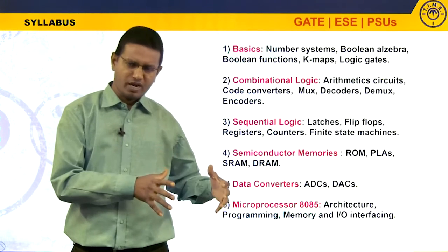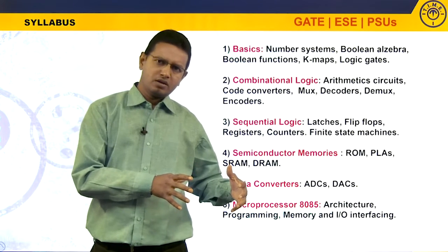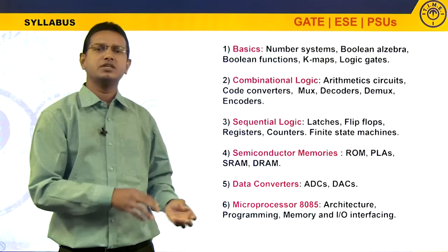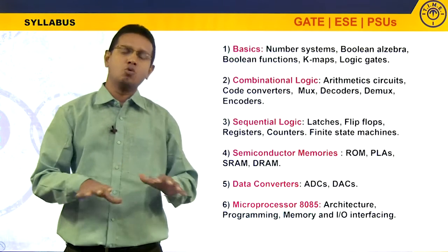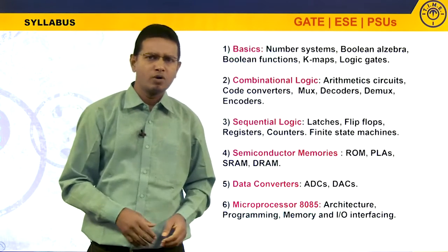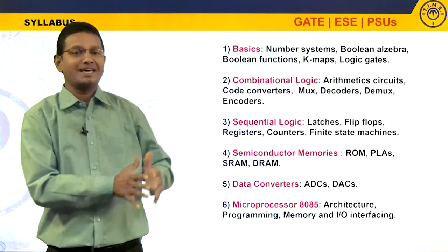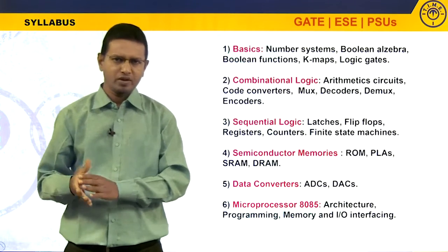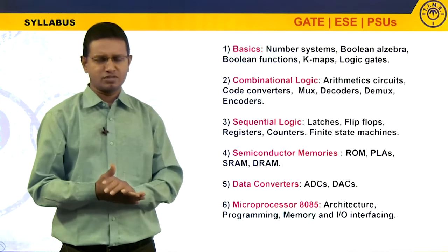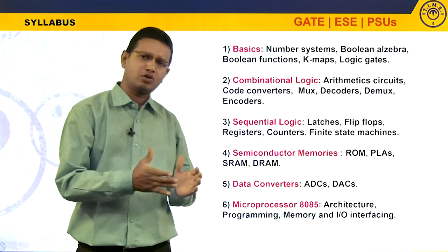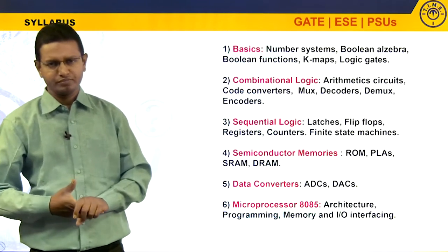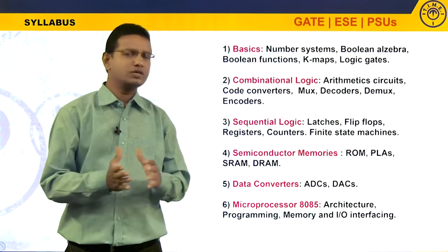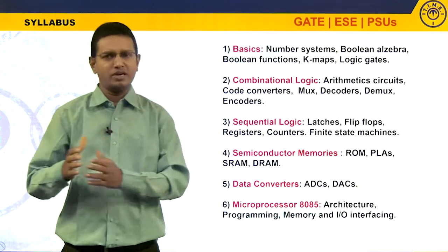In the electronic domain, especially in the digital domain, the numbers are stored in the form of bits. Wherever there is a voltage, it is considered as bit 1. Wherever there is no voltage, it is considered as bit 0. However, not a particular voltage, but a range of voltage is considered as logic 1 and a range of voltage is considered as logic 0. And based on this, there are 2 different types of systems in digital. There is a positive level logic system and the negative level logic system. And there is of course one more system called a mixed level logic system, which will include both the positive level logic system and negative level logic system.